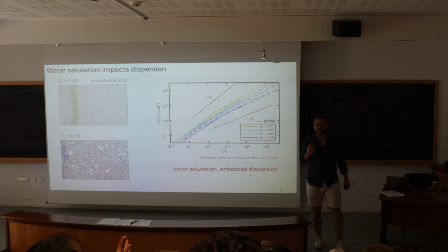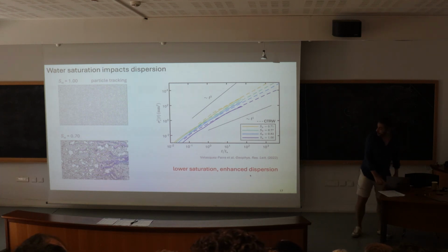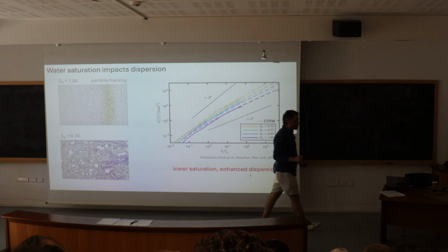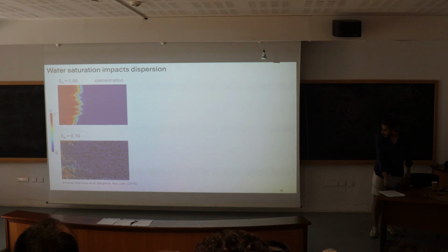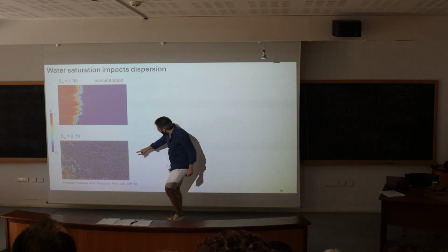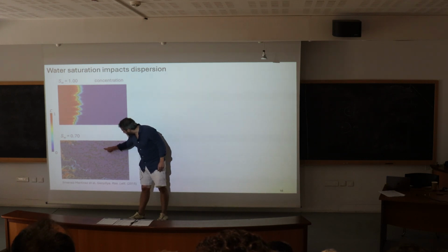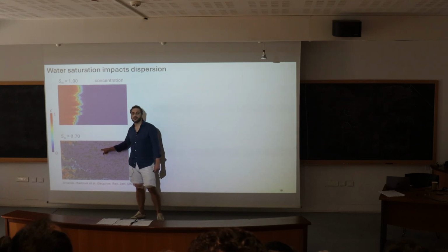So then it's like a homogeneous medium. Sorry? I mean, I don't see it's a porous medium and there are grains, no? Let's go back. What confused you is that I have removed the grains inside of the cluster of air. Let's go back to the previous image. No, it's a good point. You see here in black color, maybe it's not the best color, you have the bubbles of air with the solid grains, and in blue color you have the water. If you want to put this in a numerical solver, I don't need the grains that are in between the air, because the air is not moving.